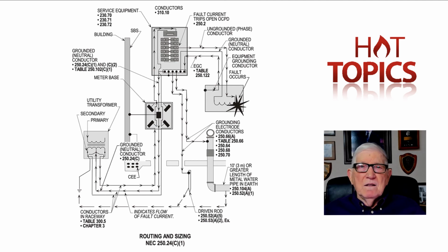Now, I'm finding in most inspections that we make that they put in a circuit breaker that has short circuit, ground fault, overload protection, but also has GFCI and AFCI all in one breaker, and they just put that in their panel board, and use that for those outlets that are required to have AFCI and GFCI protection.